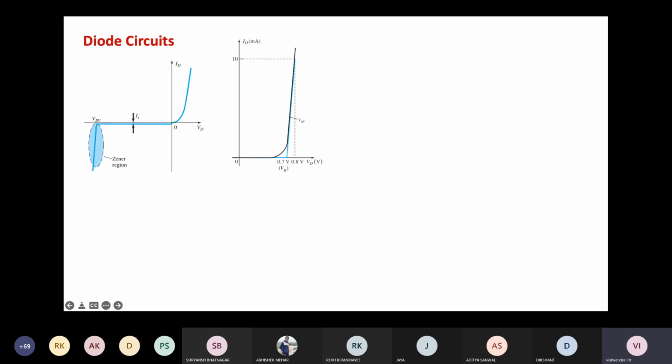Okay. So in circuit applications, whenever we have a complicated electronic circuit, diode is sitting somewhere in the circuit. Generally, it is assumed that when the diode is reverse biased, then the diode is off, which means that there is no current flowing through the diode, whatever be the voltage on the diode, unless the voltage is extremely high so that it is creating a breakdown in the diode. So until breakdown, the diode is assumed to be switched off, just like that.